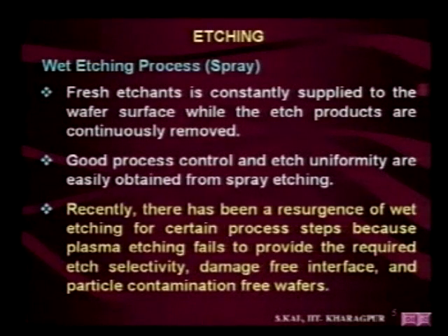If the photoresist and silicon dioxide are both etching at the same rate, then you will not have any selectivity, both things will be etched out. So that selection is in some cases very difficult. Finding an etching medium is very difficult. In those cases you may get liquid etching very easily, and that can satisfy your requirement.